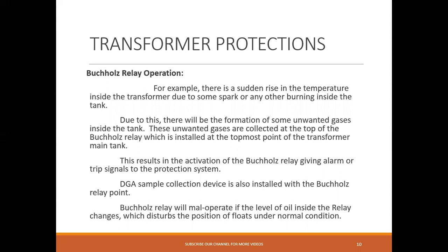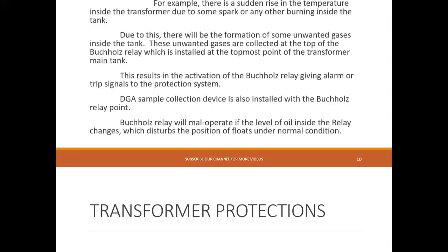The DGA sample collection device is also installed with the Buchholz relay point. Buchholz relay will maloperate if the level of oil inside the relay changes, which disturbs the position of floats under normal conditions.